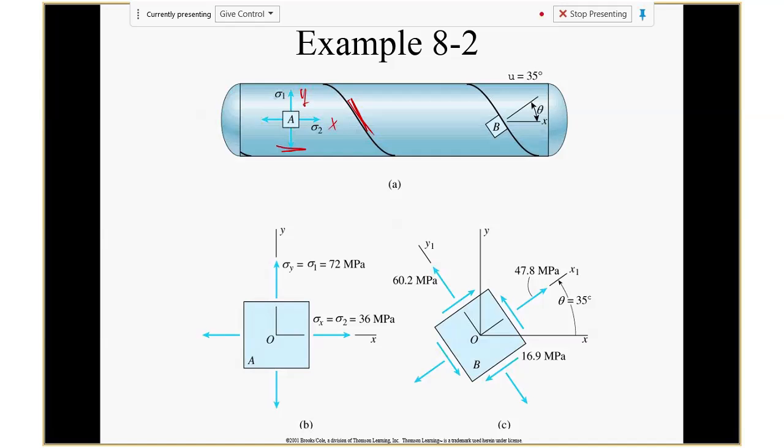Use the equation for stress rotation, right? Coordinate rotation. Or draw a Mohr circle. So you can either use the equation I just showed, or just use the Mohr circle to find it. And here is actually this cartoon showing the stress along that direction. But how to calculate, you can use the equation or use the Mohr circle, right? Because from here, let's say this one here, 36, 72, because we know sigma 2 will be half of sigma 1.